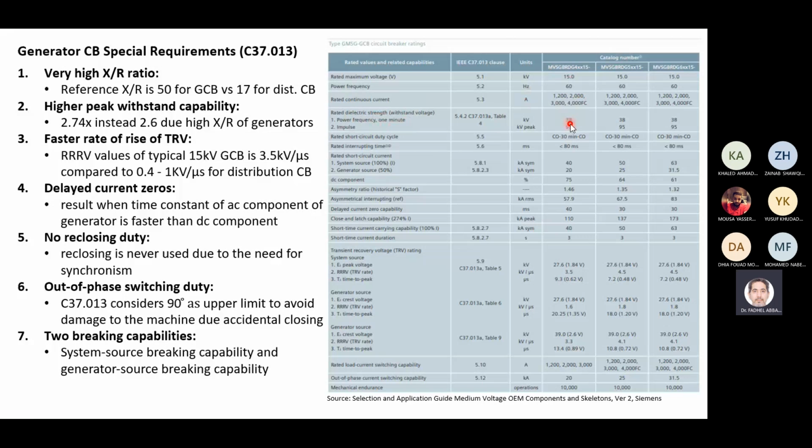If the voltage can go higher than 38 kV for a duration of 1 minute, you have to use other means to reduce the overvoltages, like shunt arresters or high-voltage arresters. There is also an impulse rating here, in kilovolt peak, up to 95 kV.